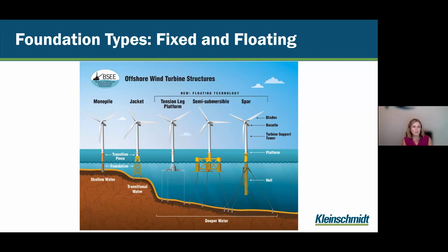And so the difference in when you would use a fixed or floating technology is generally related to water depth. And there may be other parameters that make you choose one way or the other, but for the most part, you're making a decision as to whether to go fixed bottom or floating based on the water depth. And that rule of thumb in the industry right now is about a 50-meter cutoff. So anything less than 50 meters would be shallower water, and you would be looking more at a fixed bottom structure. Anything deeper than 50 meters would put you more into the floating space. And as it's shown there on the graph, these are tethered to the seafloor. So they're not adhered to the seafloor so much as floating and then tethered to the seafloor.